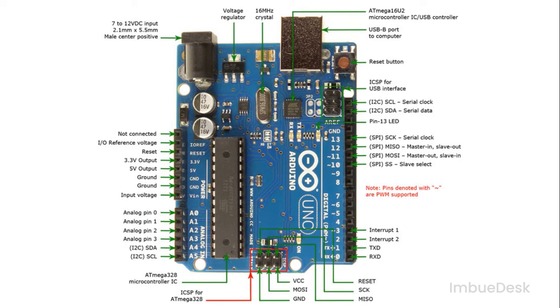In the bottom part of the Arduino, you can see some pins which are used to program the ATmega328 microcontroller and whose explanation is beyond the scope of this program. In the left, you can see 6 analog pins ranging from A0 to A5. It is used for analog values data transmission. A4 and A5 are used as data and clock pins.